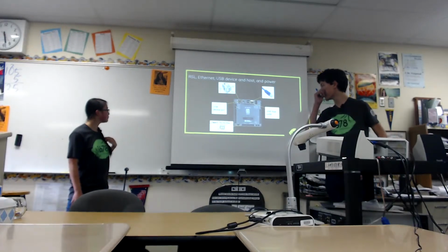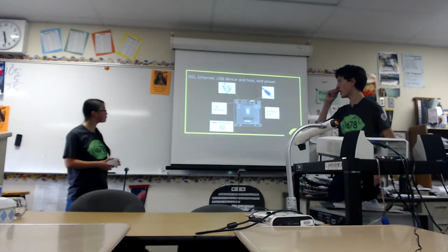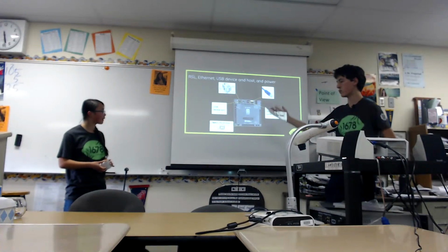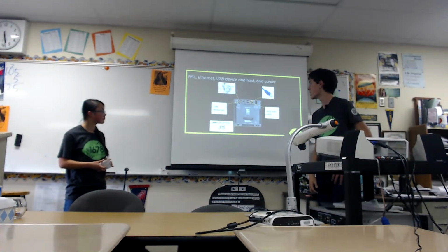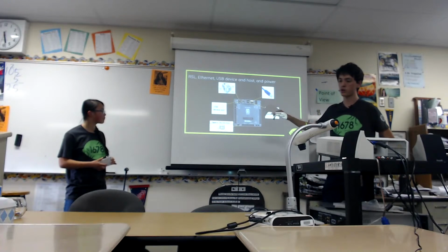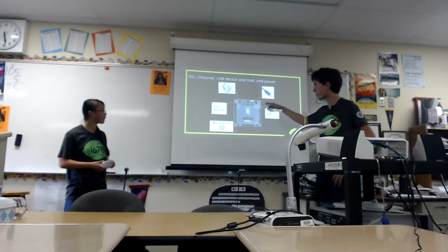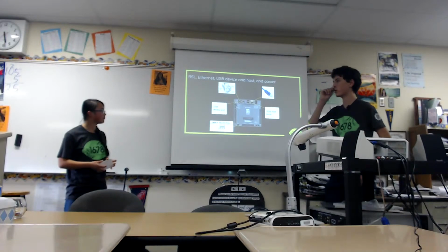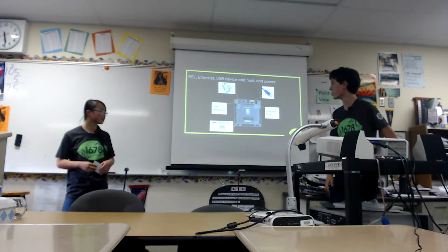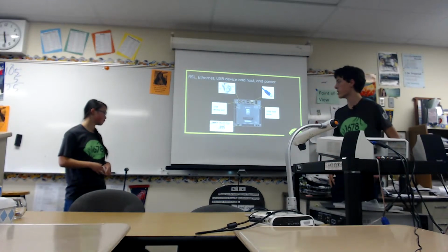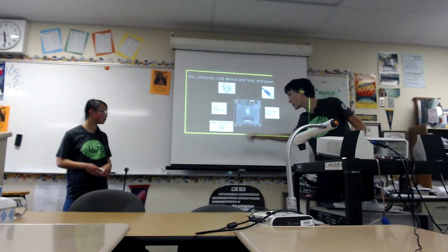So here you can see all the other ports that we didn't cover. Input is just coming straight from the PDP. Red goes in B, black goes in C. And then you've got your USB device port, for when you want to connect to your computer and control it directly. Here's your Ethernet port for communicating with your radio. And then you've got USB host ports, which I said earlier were for USB cameras. And then here's the RSL.